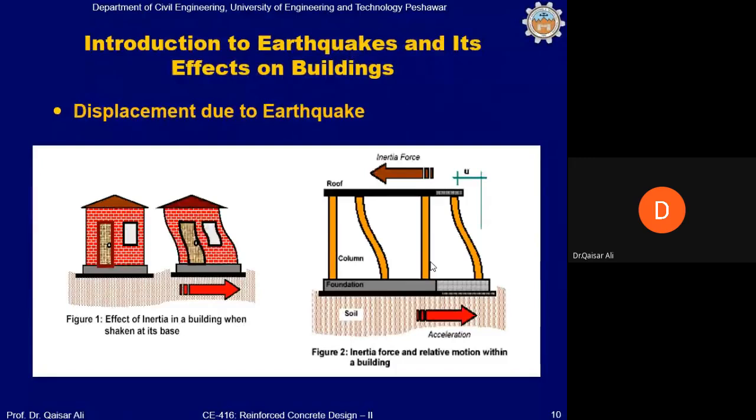Short of doing these two things, by this I mean that if we cannot make structures very, very rigid, or isolate the base of the structure from the ground, then we must design the structure in such a manner that all the stresses induced in the structure are resisted by the lateral load resisting elements, and the structure does not collapse.